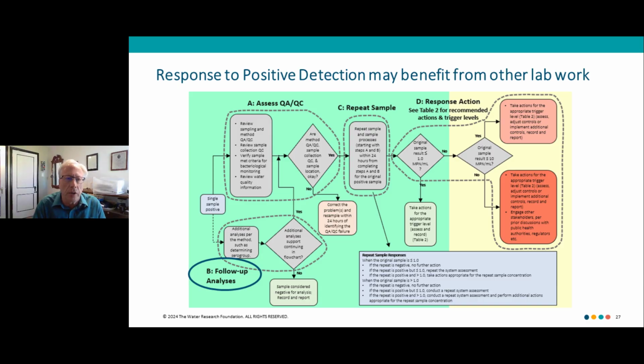Next, you get the Legionella positive sample and other analyses we could do to get a little more data out of this positive. We would process it, send it somewhere to process for serogrouping. With total coliforms, you might run an API test and look at, is it Klebsiella, Citrobacter, what coliform genus and species could this be? And that may give you some more information, maybe not immediately, but maybe in the long run as you collect more and more data.